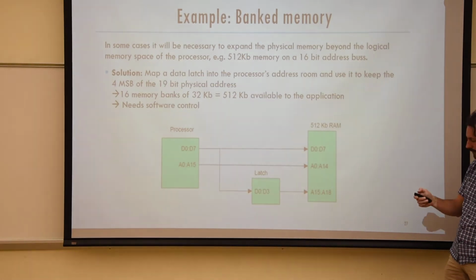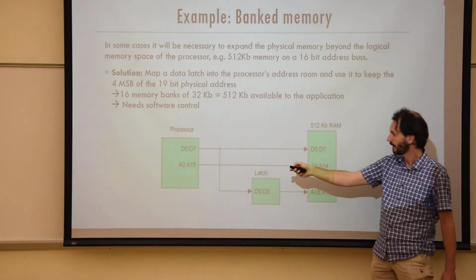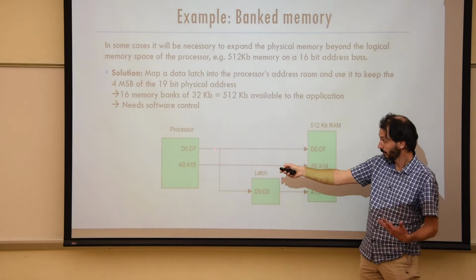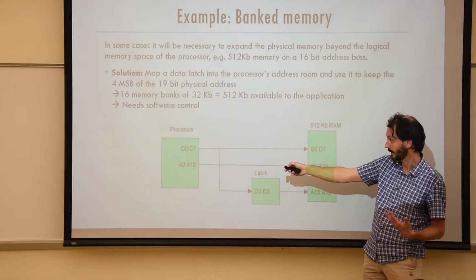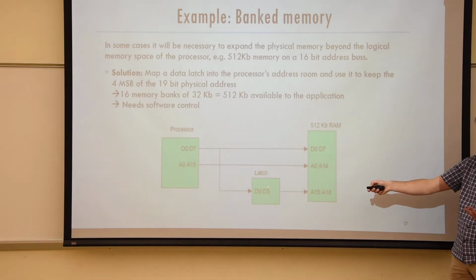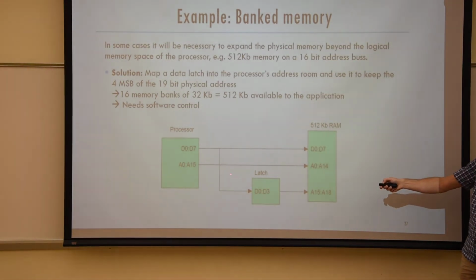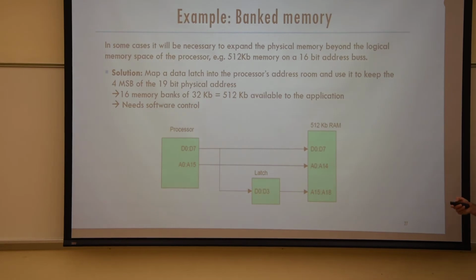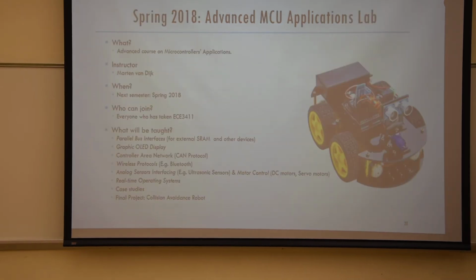Anyway, there are many solutions, but the point is that I want to show you that you can now multiplex the data lines in a way that actually helps add more address lines, because you need those in your mapping from logical addresses to physical addresses.